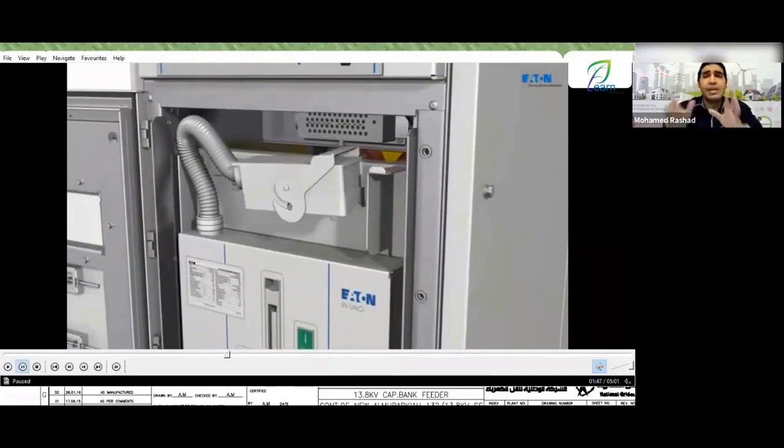Well, imagine this breaker has a closing circuit and an opening circuit and so on. So you want to give it a close, you want to give it an open. How does the breaker go in and out? Well, it has wires. These wires, my friend, must be through a plug. Why? To make it easy for you to remove the breaker or insert it again. Because if its wires are fixed, you would have to sit and disconnect the wires to remove the breaker. Right or wrong?